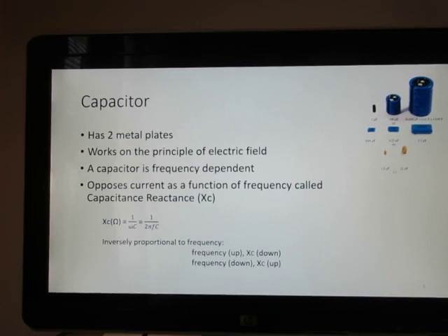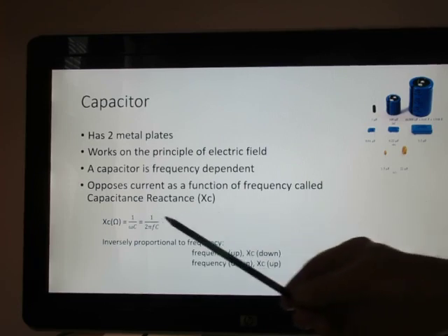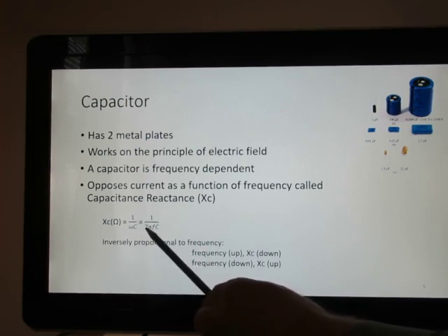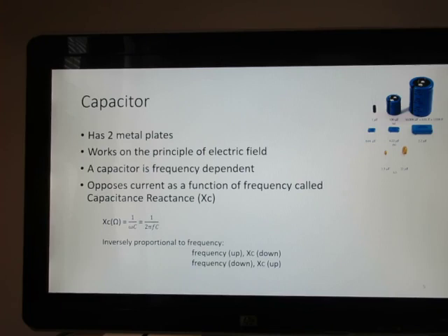Resistance in an AC circuit opposes the flow of charges. A capacitor has something that we call capacitive reactance, and there's the formula given for it right here. The units of measure on that formula is ohms. A capacitor is a function of frequency, as we can see. The angular velocity can be converted to 2 pi f times C, the value of the capacitor.